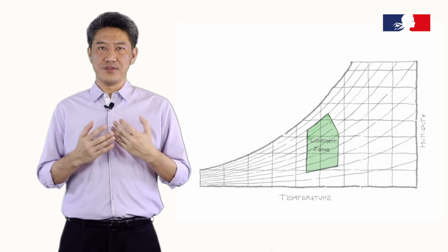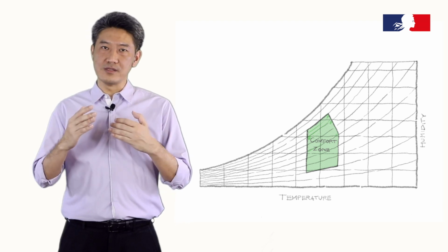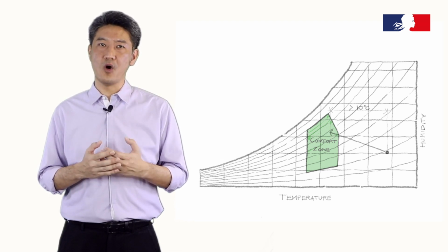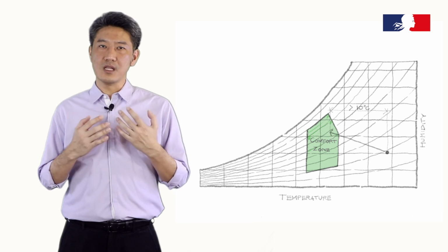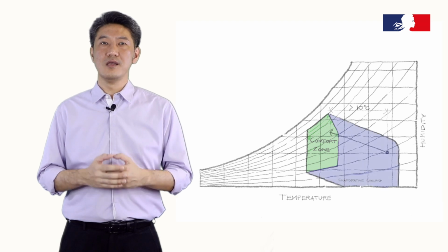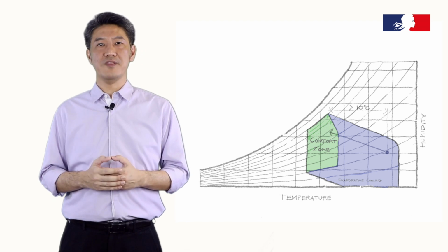In evaporative cooling, water is evaporated to cool the air. In theory, the air temperature drops while the moisture content increases. Its cooling effect can be as high as 10 degrees Celsius or more. So, the climates that are suitable for this method should be hot and dry. Daytime spaces in hot and humid climates can benefit from this method as well. In general, any water features around buildings will have such a cooling effect.